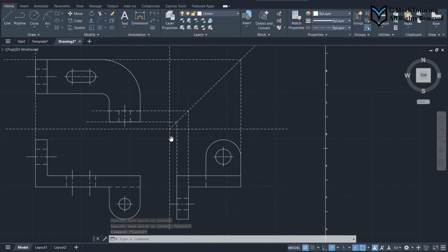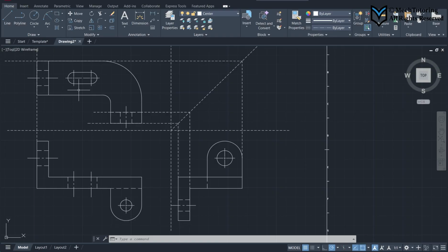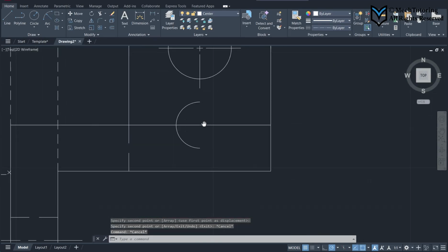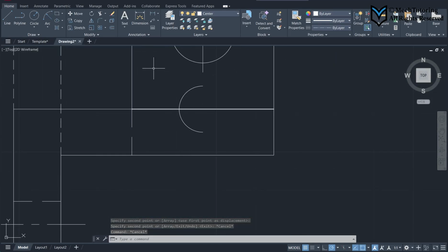And there is the slot location in this view remaining. Okay, you know that there is this slot going until that point, then going this way here. It's going to be at the middle of that. Okay, but I will do it in a special way. I'll just copy this slot and move it from this point to the middle here. And you know that there will be a hidden line at this extreme end.